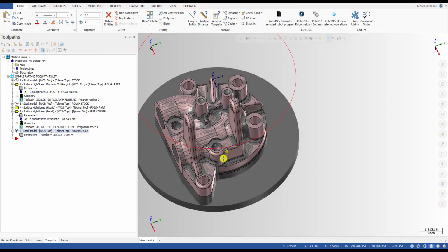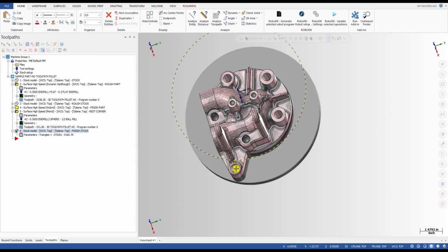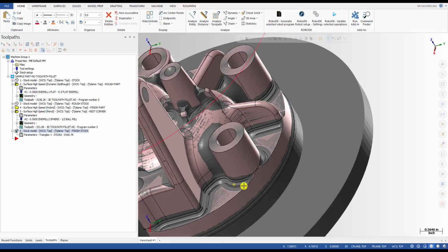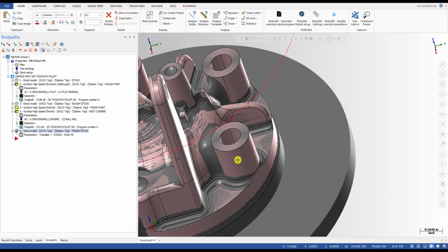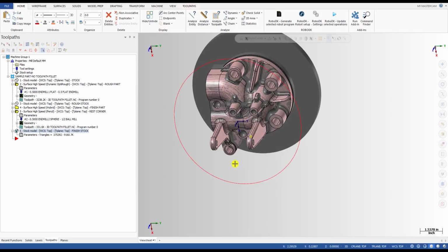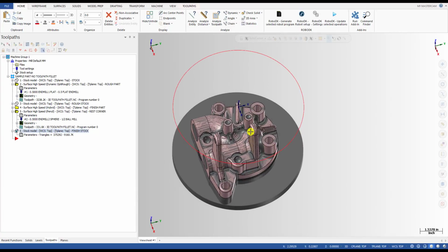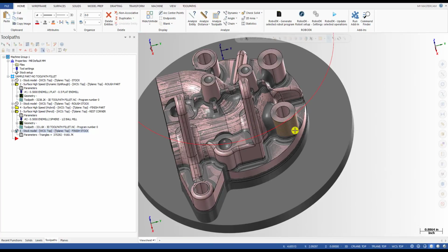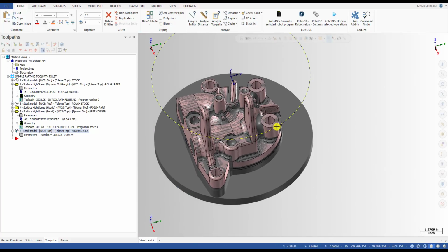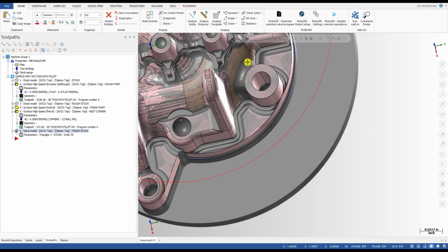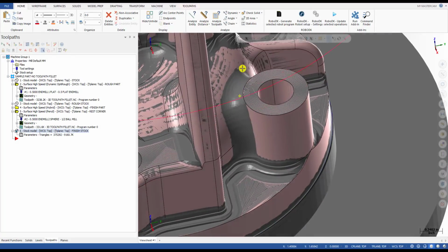And this is the stock after the finish operation. You can still see the mark from the flat end mill. The big ball mill cannot clean this corner. That's a nightmare, and we have a crazy part here. You have to use a smaller tool in order to clean this corner. So if we are allowed to use a bigger tool and we don't have to run this fillet too small, we can run the fillet like here.